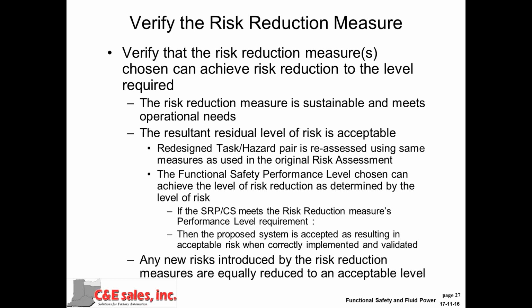Recognize also that you may be introducing a new risk based on the risk reduction measure that you might be applying. Typical example might be, and this is one that happened to me personally, we changed the source of a MIG welder wiring spool. Instead of a 50-pound, we introduced a 200 to prevent the guy from having to lift the wire and string it so often.